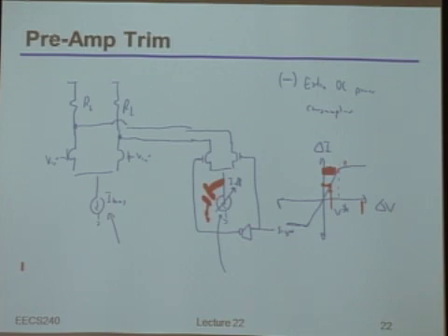Now, I've drawn things a little bit loosely, in that obviously there is still some slope on that curve. It's just that things get a lot gnarlier in terms of the step sizes you need in the current to get a certain voltage resolution out of it. It's hard for me to draw, but if it has a very, very small slope, the steps in current you need are much smaller to get the same voltage resolution on the other side. Make sense to everybody?